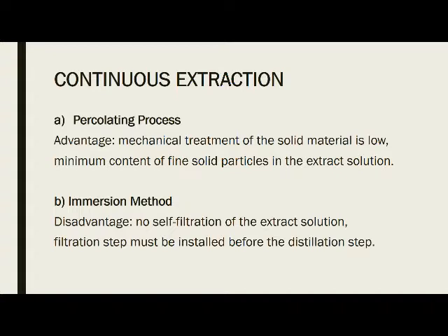Firstly is the percolating process. The solvent passes through the non-moving solid material and extracts the soluble substances. The basis for this process is that the material has good percolating properties, which means that the solvent can pass easily through the solid material. The advantage of this method is that the mechanical treatment of the solid material is low because of no movement, and further, during the passing through of the solution, a self-filtration takes place, resulting in a minimum content of fine solid particles in the extract solution.